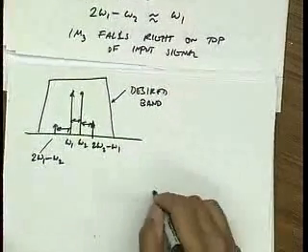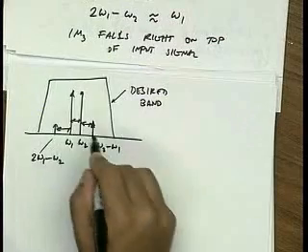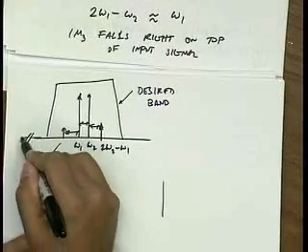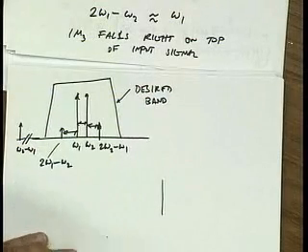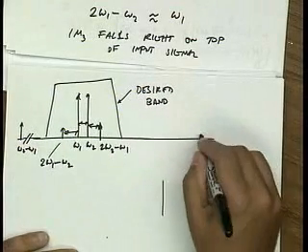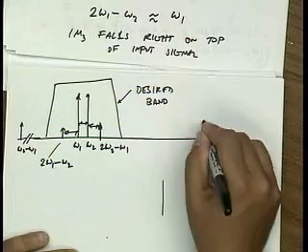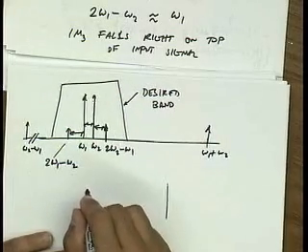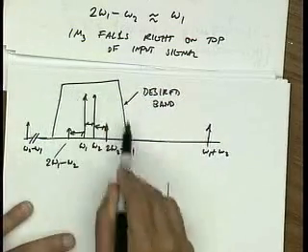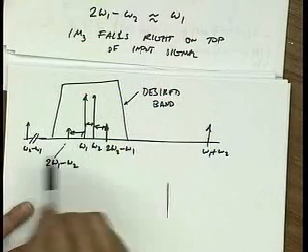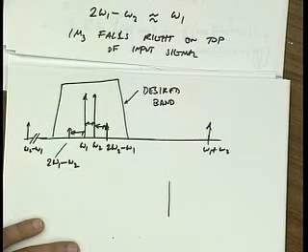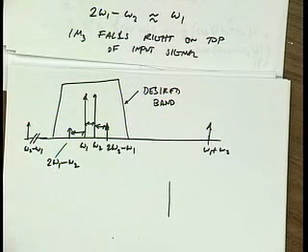All the other distortion, we could imagine a scenario where we filter them out. So for instance, I know that I'm also going to produce omega 2 minus omega 1, right? And I'm also going to produce omega 1 plus omega 2 due to second harmonic. But look, I could put a filter here and get rid of these terms. I can't filter out these terms because they're in band.